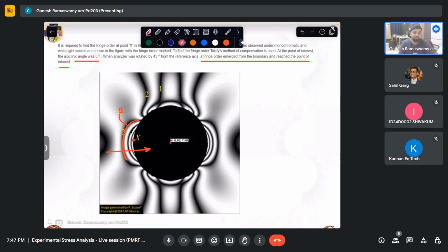Similarly, there are phase shifting techniques with which at once you can get the isoclinic angle as well as the isochromatic parameter, meaning delta, throughout the domain of interest. So these methods have evolved over time and they are matured and quite applicable to many practical problems also. But this is how the conventional photoelasticity started.